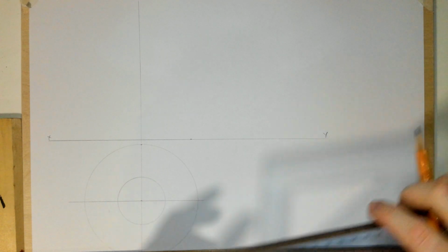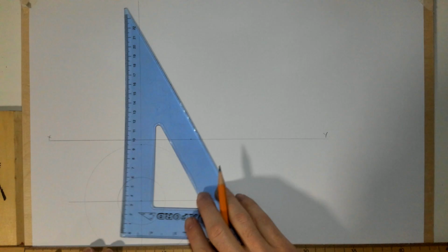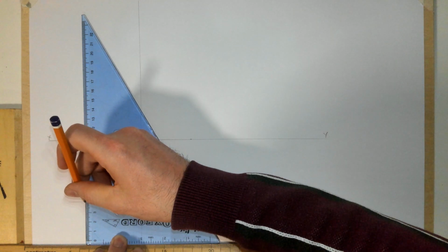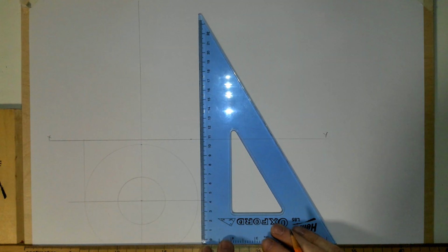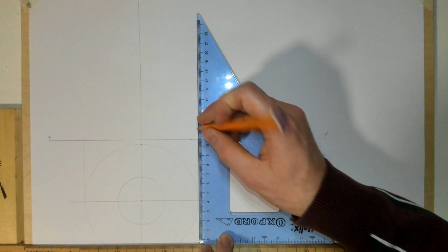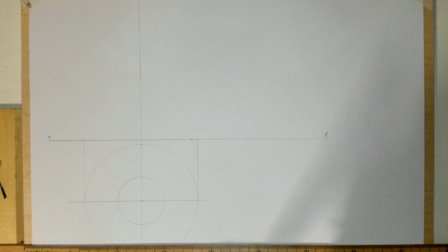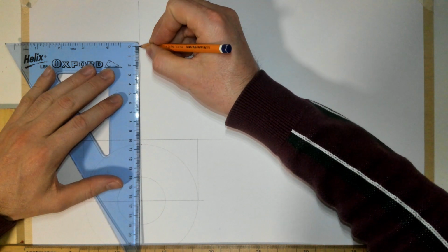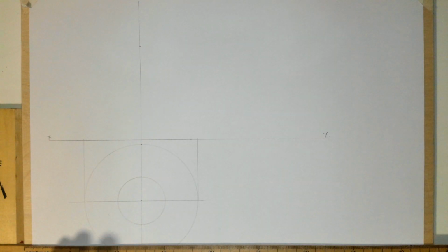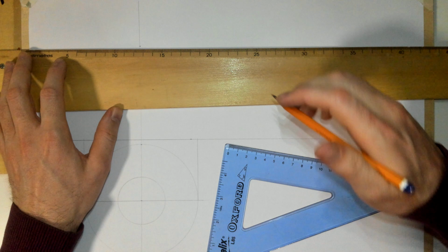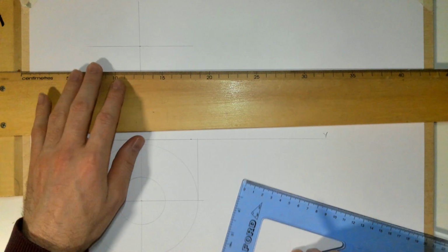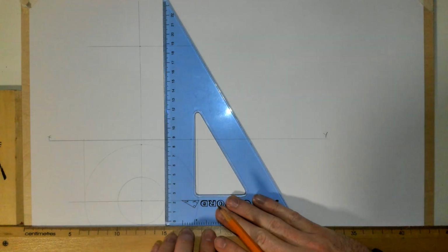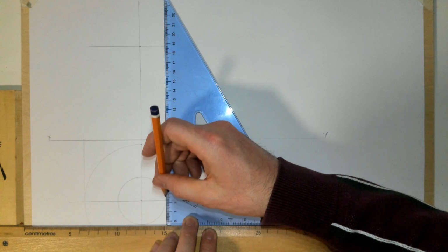Now, once you've got those two, you can bring them up to front elevation. So I'm going to bring up the outside of the big circle up to the XY line. And the middle one is up a distance of 100. So it's only half of the hyperboloid of revolution that we're drawing here. Draw a construction line across and bring up the two sides of the throat circle then.